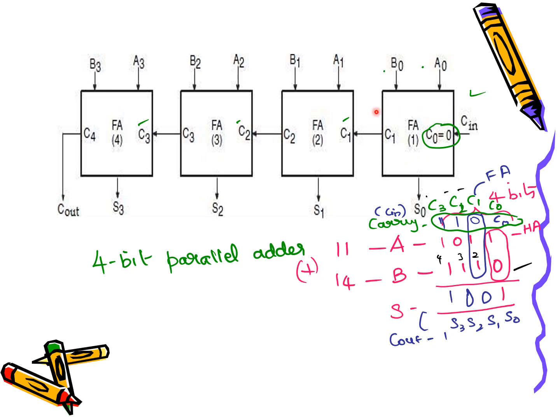Okay, so you can't draw the full circuit. Instead, you are drawing a block diagram of it. Okay, but the inputs have to be denoted. So initially you will foresee that there is no carry for the first full adder, so the third input bit is made 0.